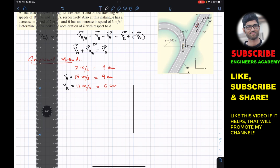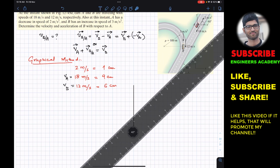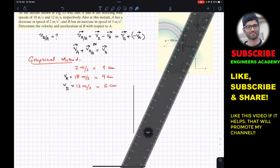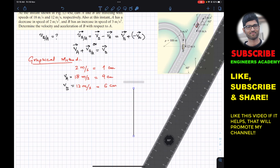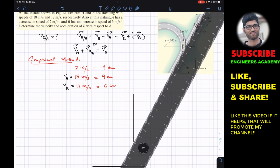Similarly, V_A is 18 meters per second, and it is making 60 degrees with the horizontal. So we need to draw a line of 9 centimeters at an angle of 60 degrees. First of all, we have to set the 60 degrees and then we have to draw the 9 centimeter line from the 0.